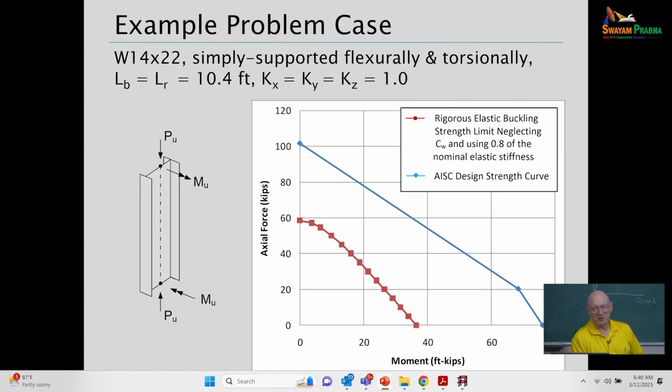A boiler building, if you're not familiar with it, is a building basically housing a boiler, a big boiler on the interior. You have nowhere to brace your columns because there's a big boiler there. They go way up, and you're supporting the boiler from the top of the building. So you basically have a very long unsupported length of your columns, at least in the direction in and out of the plane of the wall of the building.